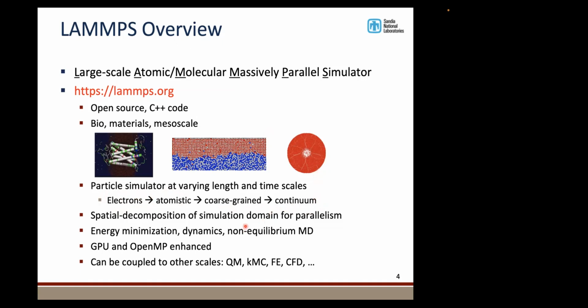We use domain decomposition for parallelism. LAMMPS supports minimization, dynamics, as well as non-equilibrium molecular dynamics. We have support for accelerators, and LAMMPS can also be coupled to other length scales such as quantum mechanics, kinetic Monte Carlo, finite element, and computational fluid dynamics.